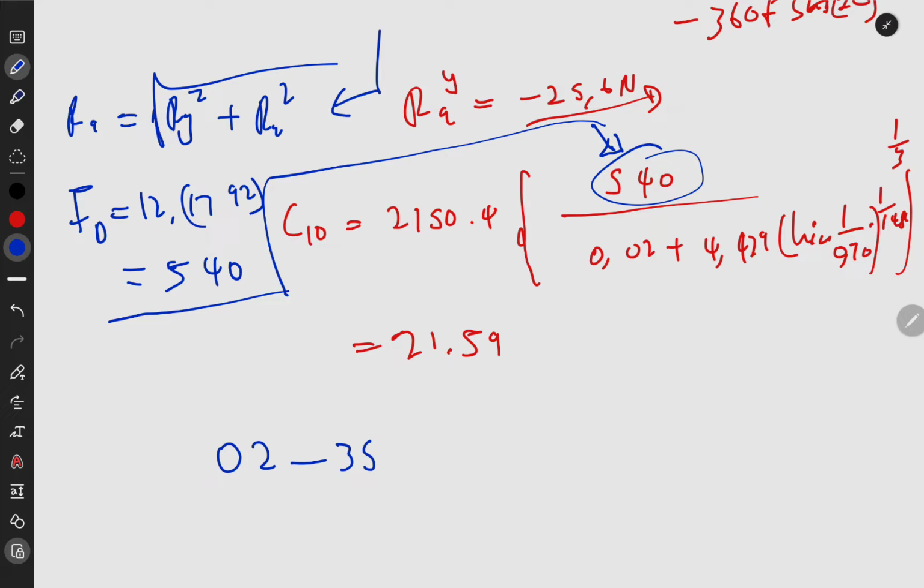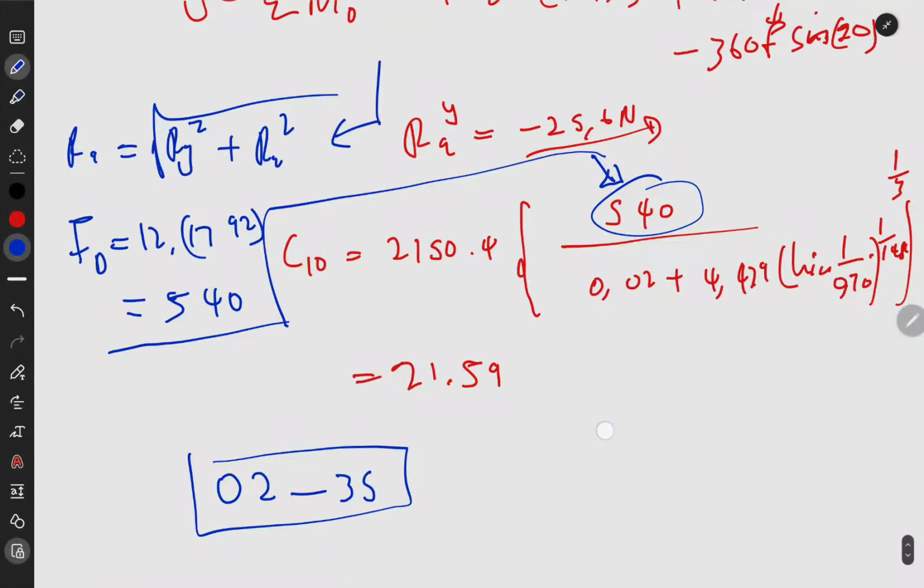Okay, remember we're looking for good lifespan and whatnot. Also take note that these bearings perform like this if they are in a good condition, where maybe they are properly lubricated and well taken care of, and installed properly. So you can just go through the SKF websites for all these parameters in the table and how to select, if you want properties for each bearing that you are looking at, their lifespan and whatnot.